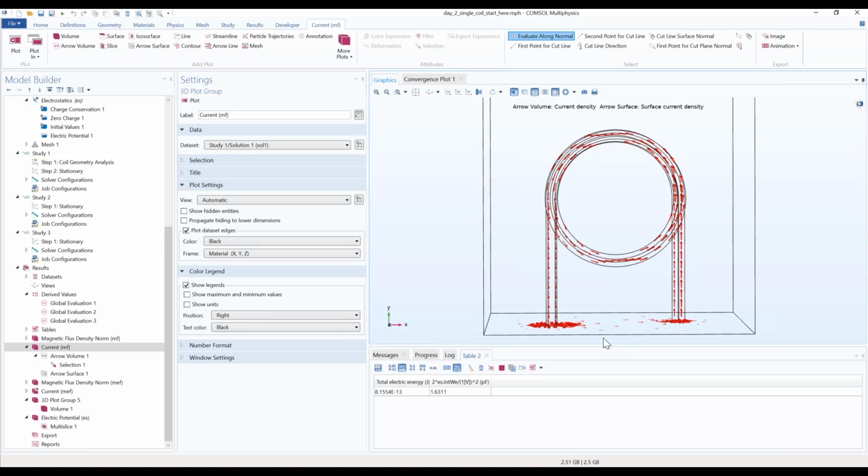So there is an effect of this magnetic insulation. This does have an effect on the overall inductance of the model. If we were to change the distance to that boundary, it would affect the model results in terms of the inductance. So what we have here is a coil above a ground plane. That's one interpretation that we can have of this model. The other interpretation of these magnetic insulation and perfect magnetic conductor boundary conditions is as a kind of symmetry plane.